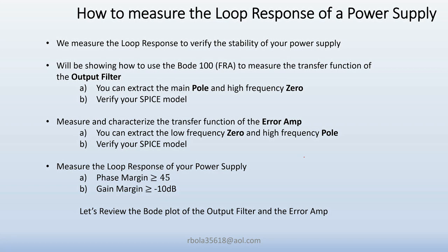Welcome to how to measure the loop response of a power supply. In this video, I'm going to measure the loop response, and one of the reasons that we do that is to verify the stability of your power supply. That's one of the biggest things: if you don't design your compensation specifically, then you're going to have instability. You might have oscillations. If you measure the loop response, then you can verify that you're not going to have any conditions where it's going to oscillate.